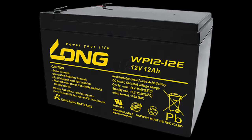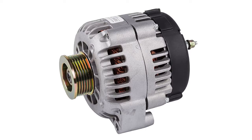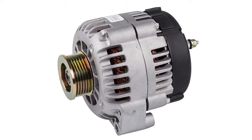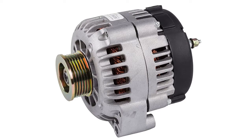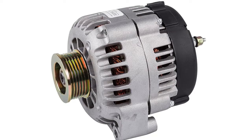The anode is made of lead. The cathode is made of lead dioxide. The electrolyte is sulfuric acid. A surplus of electrons gathers at the lead anode. This happens due to the reaction of lead with bisulfate from the sulfuric acid. These surplus electrons then move to the cathode via the vehicle wiring, powering the car in the process. The alternator, a generator attached to the engine, reverses this reaction during engine operation, recharging the battery.